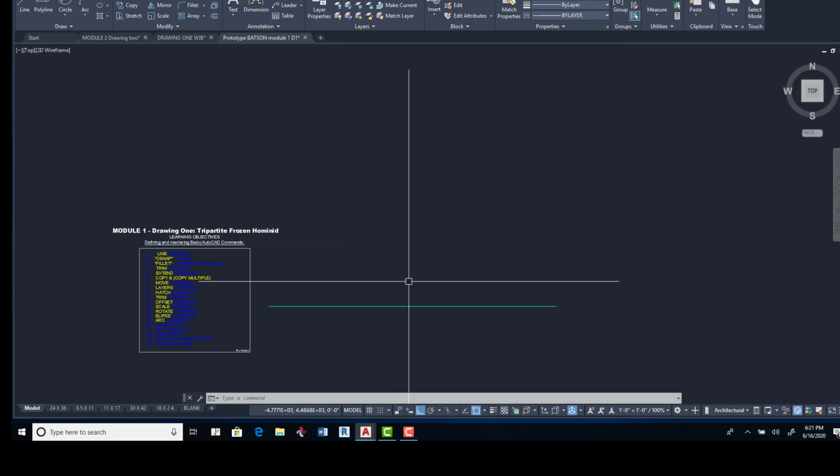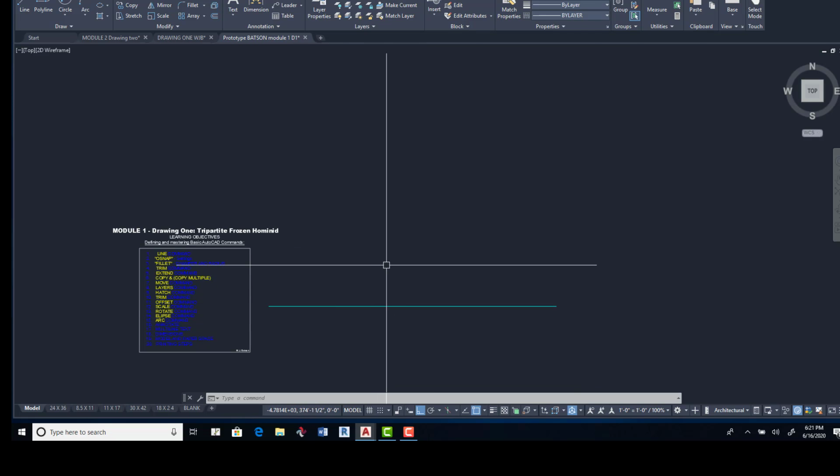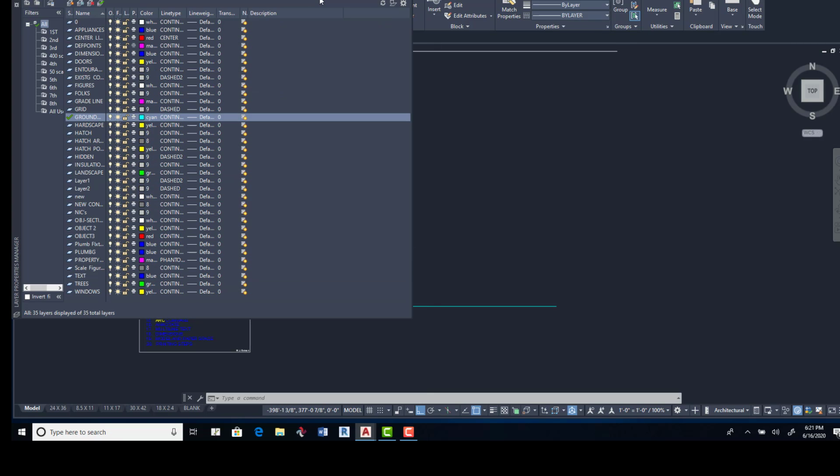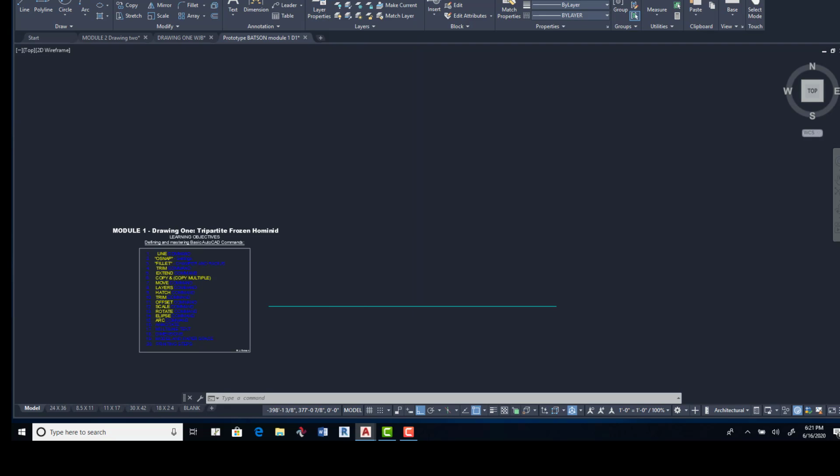Now we're going to draw the object. So now we have to be in the object layer. So let's go up here. Click here to the layers. Let's go to the project object 1. So it's just an object section. There you go. So double click, and the red check is there. That's good. And it says object section. It's white, and it's by layer, by layer, by layer. That's cool. So now let's go to the circle command and draw the first circle.